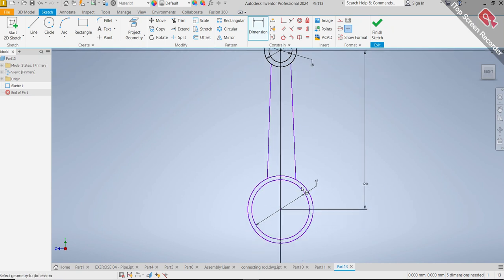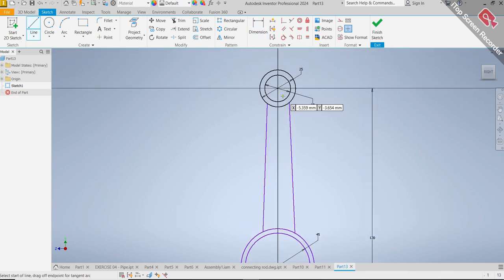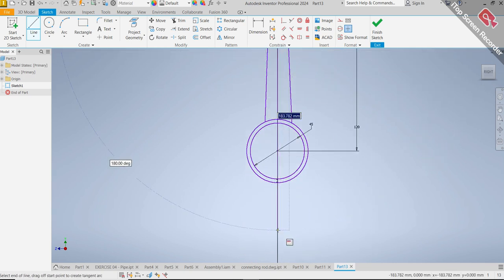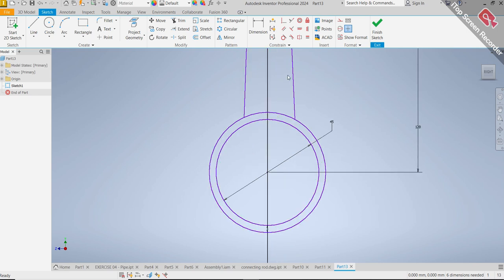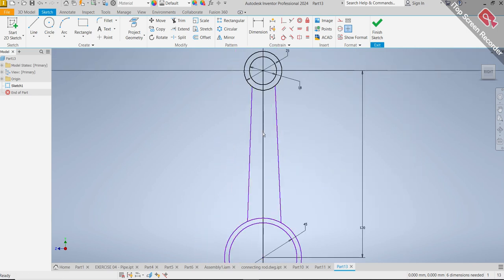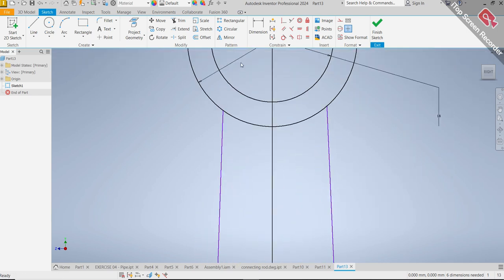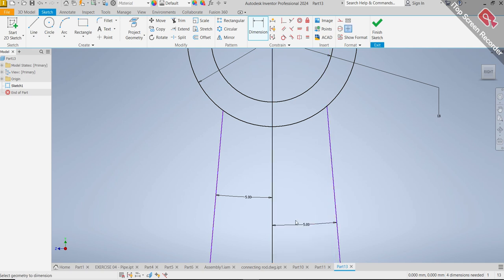Next, I'll just create an invisible line, just a line from this point just down to this point, so I can do my dimensions. Now for dimension, I'll click here from this point, this line to this line. There's an angle. I'll make it 5 degrees. I'll come here, this point to there, 5 degrees. So I'm good with that.